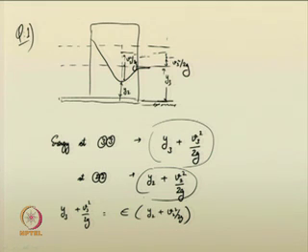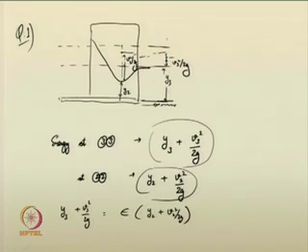For flow to occur from section 2.2 to section 3.3, definitely the energy, the total hydraulic head, at section 2.2 has to be more, right. So, we consider here the energy at section 3.3 is some fraction of energy at section 2.2. So, epsilon can never be greater than 1. The maximum possibility is that there will not be any energy loss. So, epsilon is equal to 1.